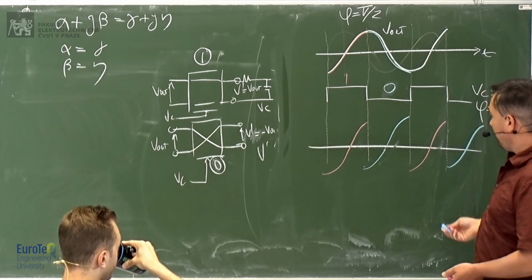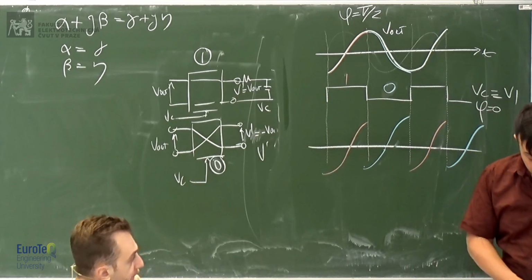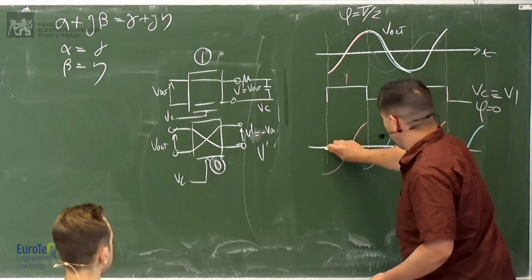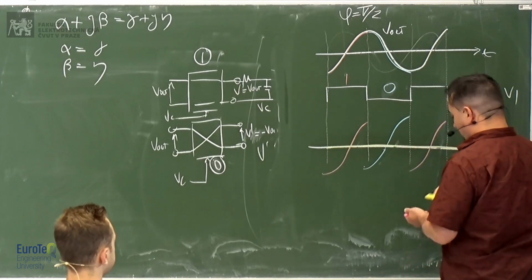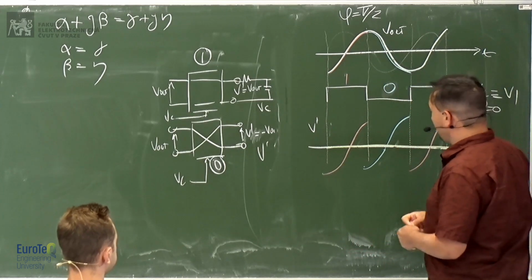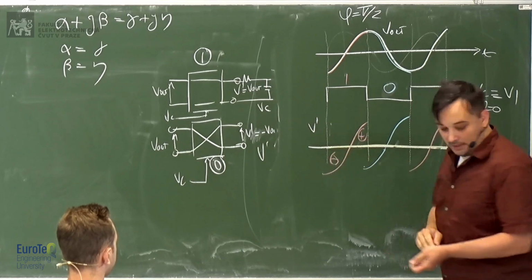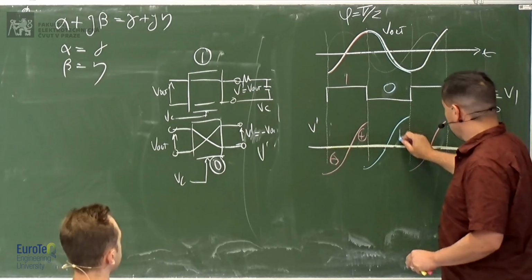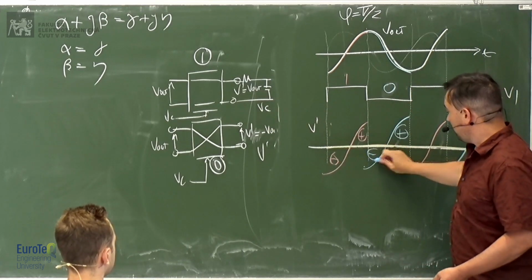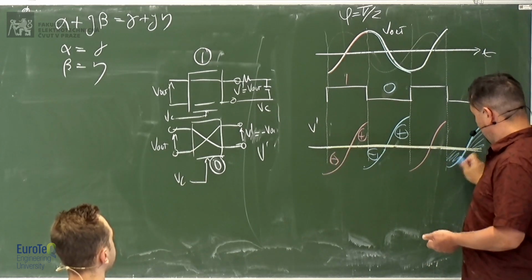Now, the average that you get after your low-pass filter is going to be 0, okay? So if you take the average of this V prime, this is going to be 0 because this positive part gets cancelled by this one. If you put this through an LPF, you get the average, so this is cancelling this, and so on. Oh, so that's how the DC value corresponds to a phase shift.